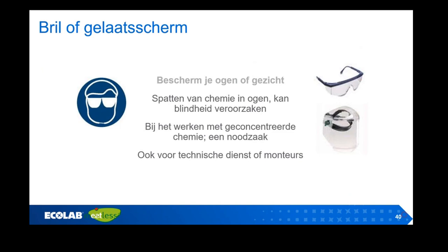So when you work with concentrated products, I always recommend the goggles and the face shield. Yeah, because we saw the pictures. It's really shocking. Especially with alkaline products, you don't immediately feel pain. With acid, you feel it directly, but with alkaline, it can take hours before you notice. It slowly dissolves your tissue, and then it's too late.